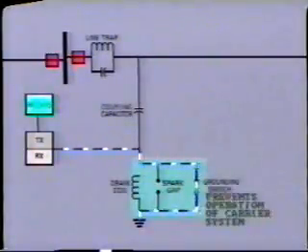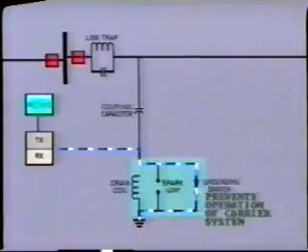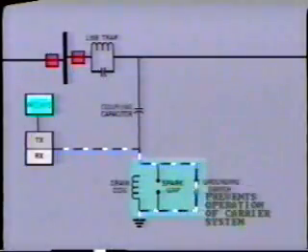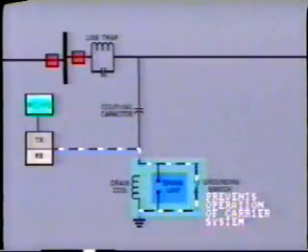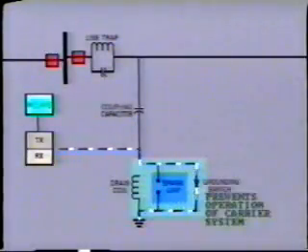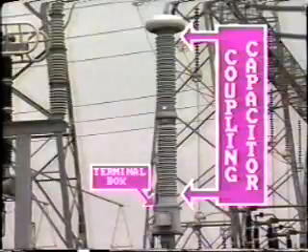The carrier grounding switch connects the signal directly to ground and effectively prevents operation of the carrier system. This could also occur inadvertently due to protective gap failure, such as foreign material bridging the gap. Regular inspection of the carrier accessories is necessary.